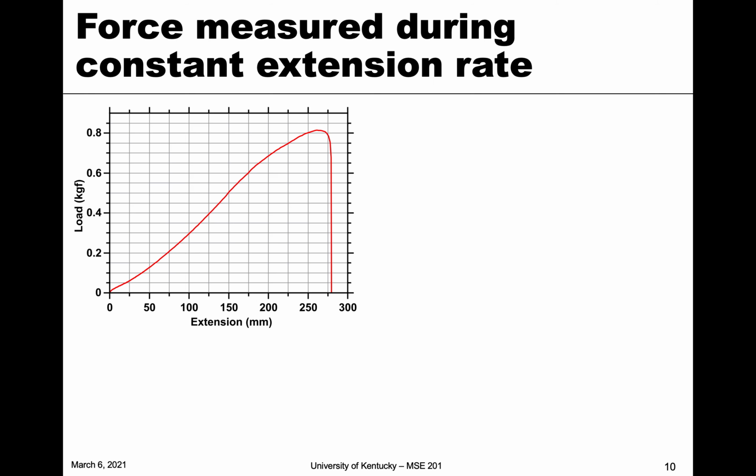And so the result of that was a load versus extension plot, right? So if you extend it some distance, what force or load does it take? This extension has units of millimeters, and the force here was in kilogram force. And so this is what it looked like. If we extend it, we have to apply some amount of force, and that force keeps going up the longer we extend it. And then at this point, it either fractures or the test is over, so it goes way back down. Right. So that happened for this sample that you saw before.